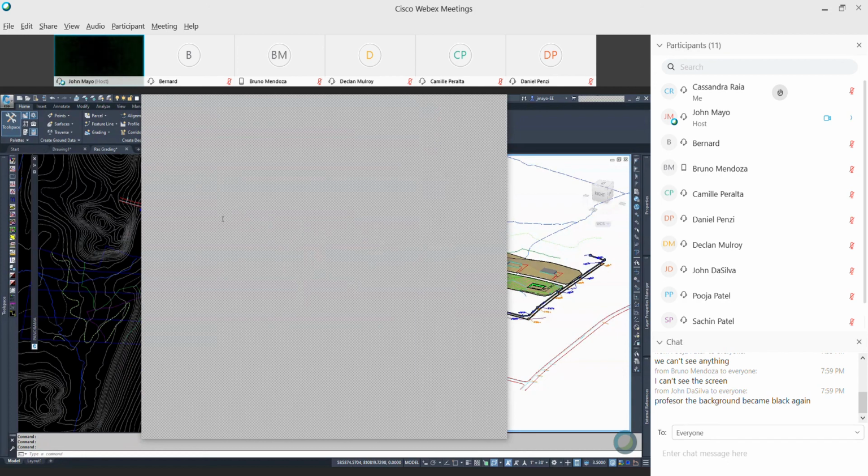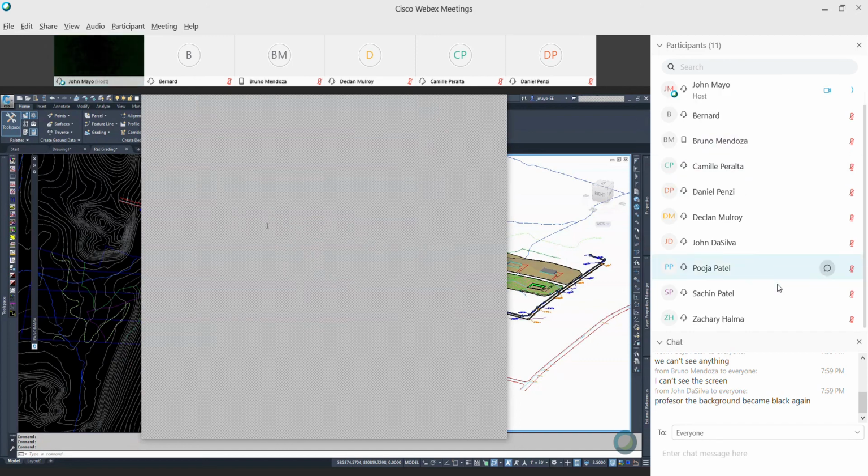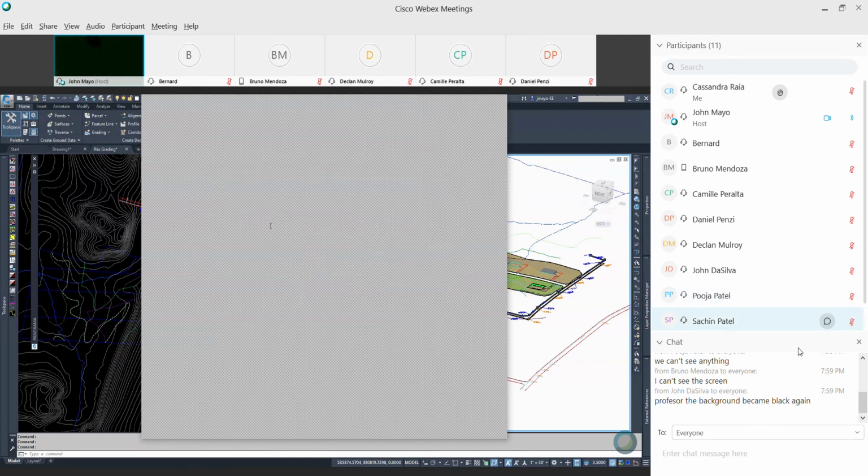Now just remember, topographic features in this case means not just contours, but also buildings and driveways and stuff like that. But in your subdivision plan, you should have no elevation data. Remember that from submission 1. That's an exception to this rule.